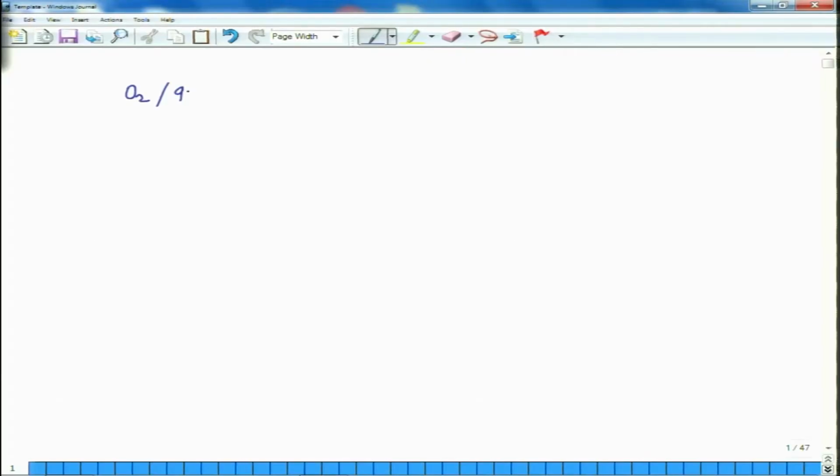and also other semi-infinite plates, we had stated that for the lamination sequence 0 to 90 to 0, this type of lamination sequence, B16, B26, D16, D26 and A16 and A26, for these types of plates all these terms are 0, because it is a cross ply laminate.